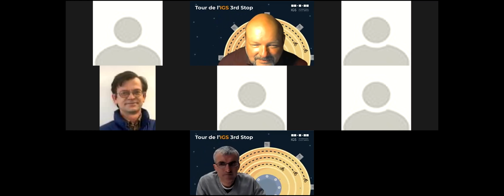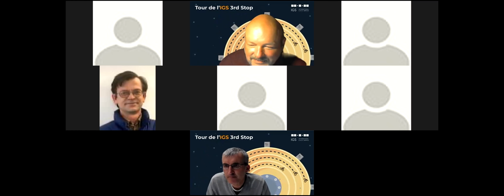I am Bruno from Uganda, and recently I did a static observation then processed using PPP, but unfortunately, when I looked at the type of solution, it was a code. And when I looked at other reports that I had processed before, they had a phase fixed. So I really wanted to know what is a code solution and what are the causes in PPP in particular. Thank you.